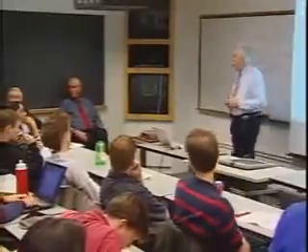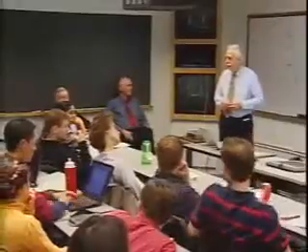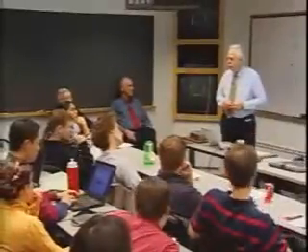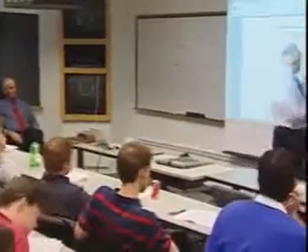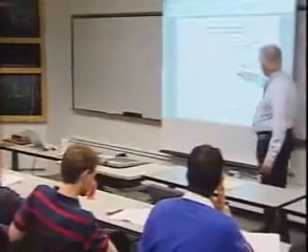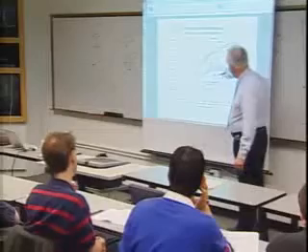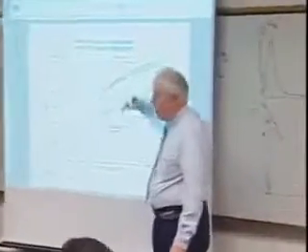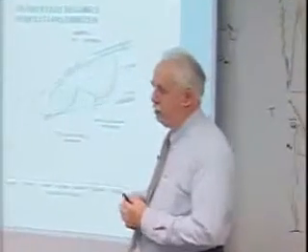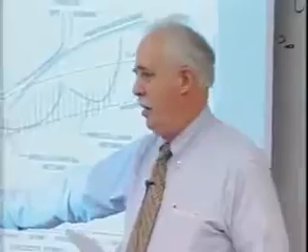Yes. A couple of questions. Sure. One, the Apollo lines. Just trying to track it. Why did they come back up? That was the basic flight mechanics, to dissipate the energy. And actually, I'll get into this a little bit more on the next chart, and then go through an entry. You wanted to not exceed the deceleration. Actually, from an ablator standpoint, one of the most efficient ways to come in is hot and heavy.